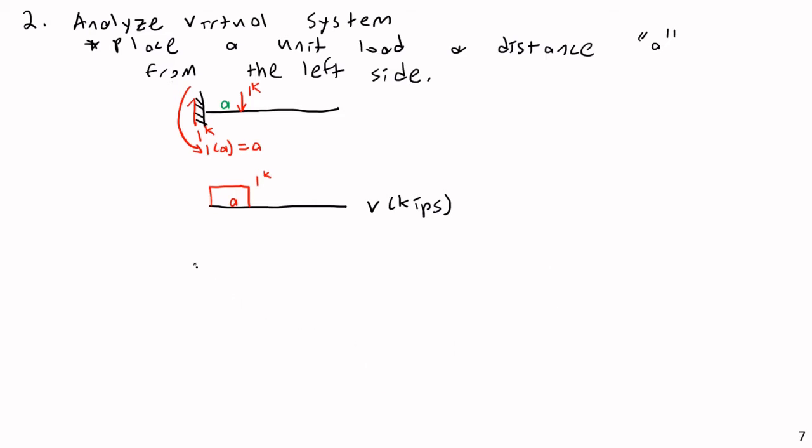Then let me find the moment. And of course, this is a cantilevered beam. So beyond the location of our furthest most load, we have no more moment and no more shear. So because this load is not at the end of the beam, we will actually only have moment and shear over this first region of the diagram.